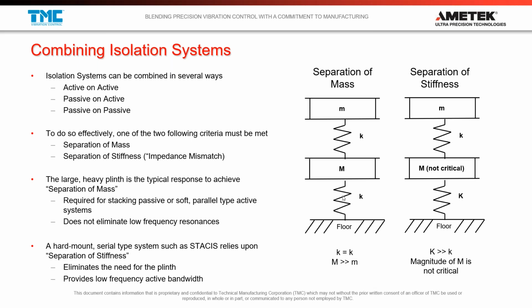So you're going to have this system resonating at some frequency. Then you're going to add that resonance to this resonance, and that's going to resonate at some frequency. So you're going to have really bad low frequency performance if these are soft springs. But then you're going to have awesome high frequency performance because of the summing of the transfer functions.